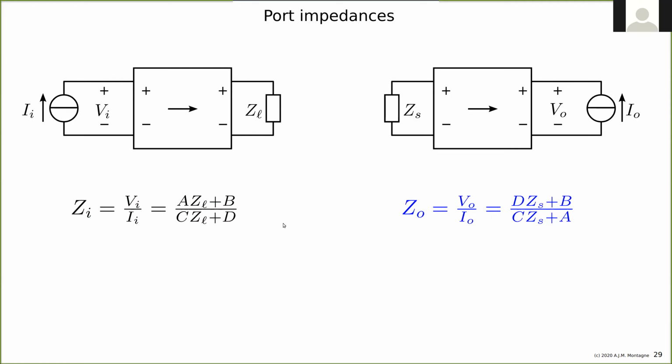So you could also, with these two formulas, design a voltage amplifier, because we need to have a combination. ZI needs to be infinite and ZO needs to be 0. How do we get that? Well, then you will arrive at the same conclusion: this can only be done if C, B, and D are 0 and A is finite.